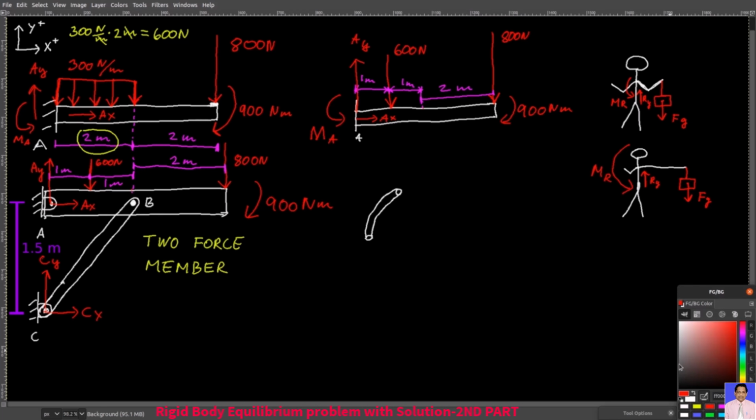A two-force member is a structural element that has one force applied on one end of the member and another force on the other end of the member. And the thing about two-force members is that in order for them to be in equilibrium, meaning that they can neither translate nor rotate, three conditions must be met. First of all, both forces on both sides of the member must have the same magnitude. So F1 equals F2 equals, let's just call it F.